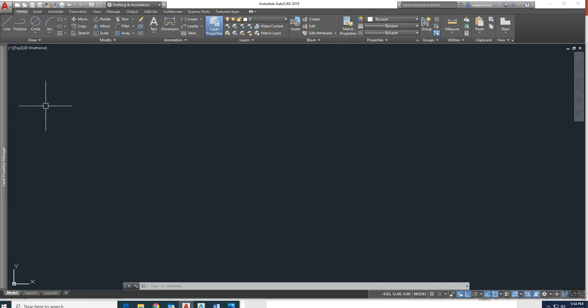Okay. So here's my line. Again, if I click, I can initiate a command by left clicking it. And once I left click it, there are two things that are going to happen. First, you can see my command window here. It says line, letting me know that I've initiated a line, and it says specify the first point.